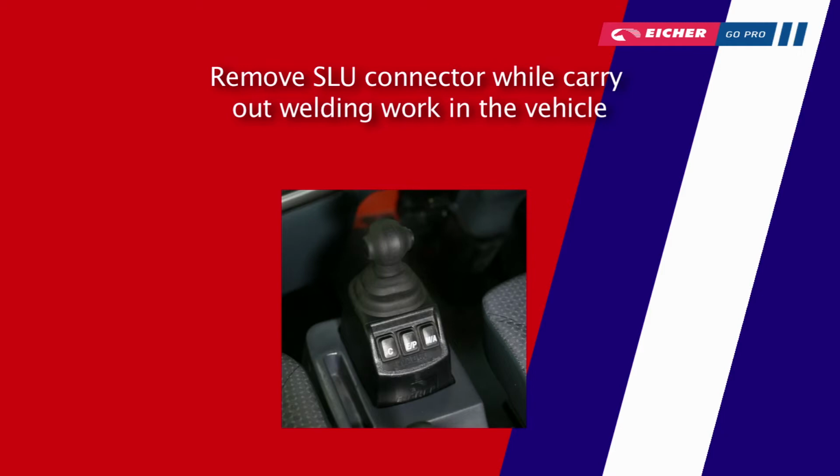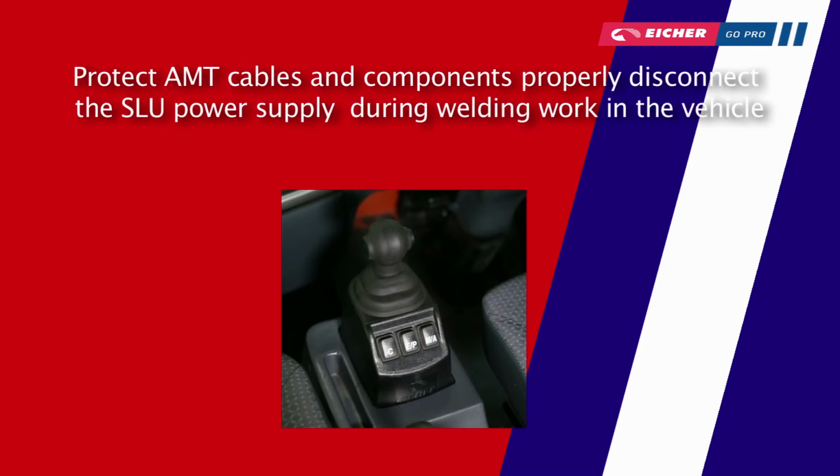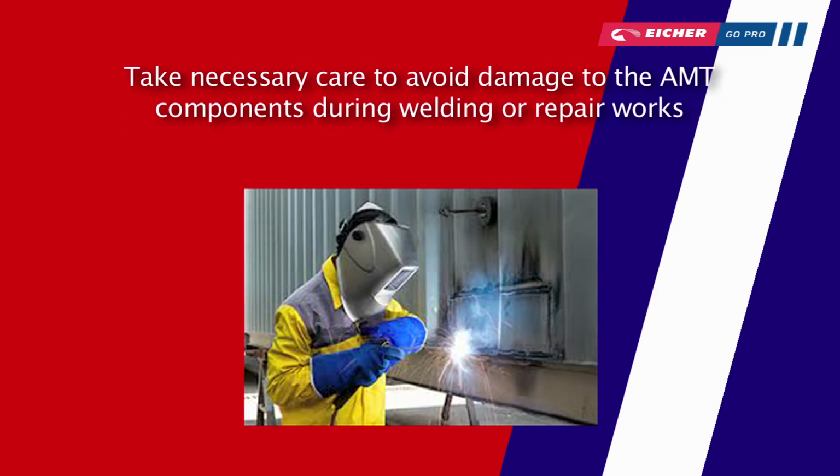Remove the SLU connector while carrying out welding work in the vehicle. Protect AMT cables and components properly. Disconnect the SLU power supply during welding work in the vehicle. Take necessary care to avoid damage to the AMT components during welding or repair works.